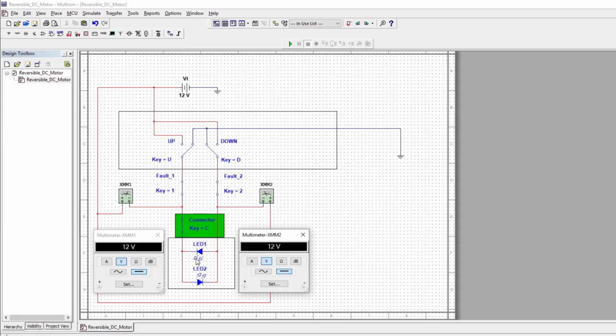switch to the motor. Now the motor, I made them LEDs pointing in opposite directions, okay, and that will give you an indication of this motor. You don't have one motor for up and one motor for down, or one motor for forward and one motor for reverse. It's simply a reversible DC permanent magnet motor. All right, so you switch the polarity, it rotates the other way. So the visual cue here would be LEDs opposite each other, and you will see one light with one polarity and the other light with the other polarity.